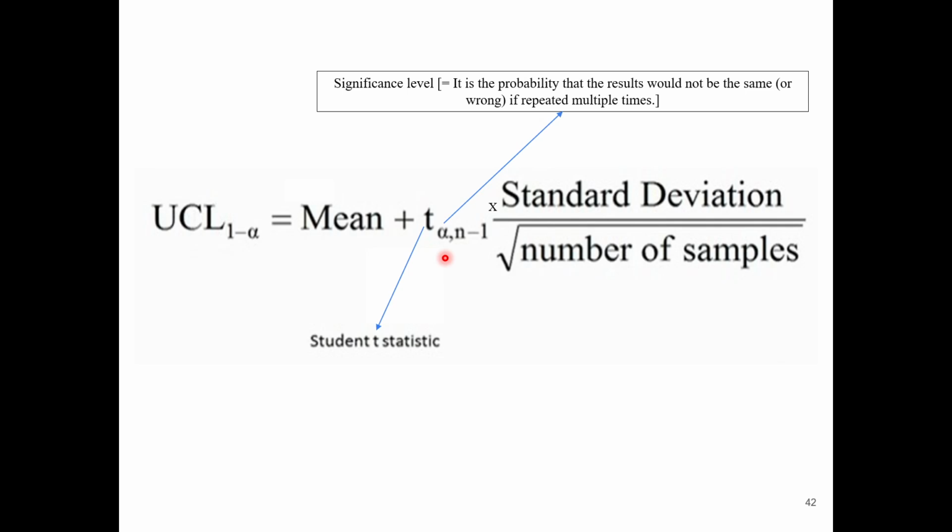That means it has an alpha value of 5%, and generally we always take a confidence level of 95%. That means we allow a 5% chance to go wrong. Even for compressive strength in concrete, we always take the characteristic compressive strength, which is the compressive strength with 95% guarantee. Out of 100 cubes, 95 cubes will have at least that strength, but there can be 5 cubes with a lesser strength, a maximum of 5, not more than that.